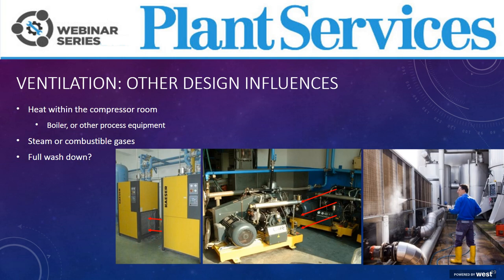Other ventilation influences are other equipment in the room. So we saw that with our original example with those 2 compressors side by side. Cooling air discharge from one piece of equipment can easily be ingested by another. Further, if there are other gases within the compressor room, those could potentially be ingested into your compressors and dryers. Lastly, if your facility is a full washdown facility, be sure to consider where you put your compressors or what type of protection you have for these units. Note that most machines are only a NEMA 12 enclosure and are not rated for a full washdown.